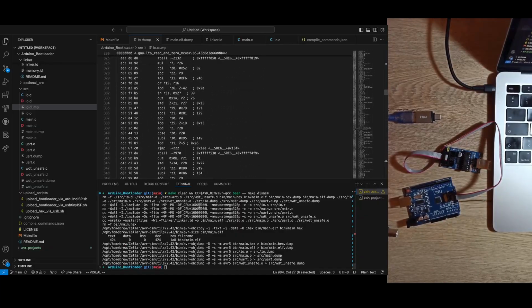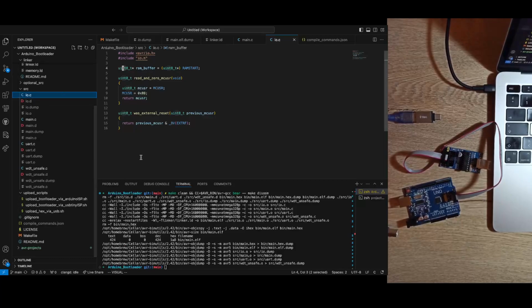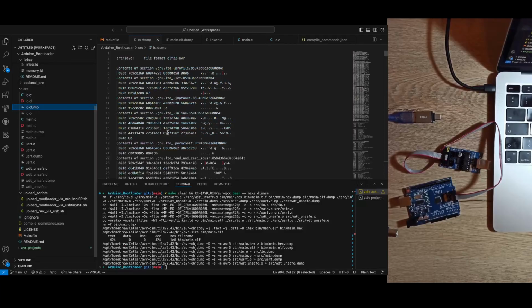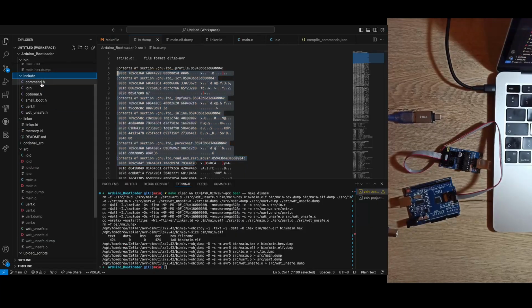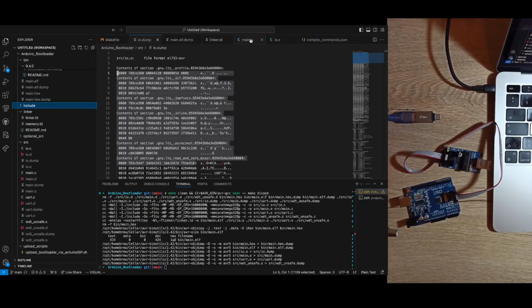This is an intermediary description of my translation unit, the C file. It's an intermediary representation, not compiled exactly. These intermediate representations are used for deferring certain optimizations to the final linkage stage, where we get the main elf. So that's the difference.